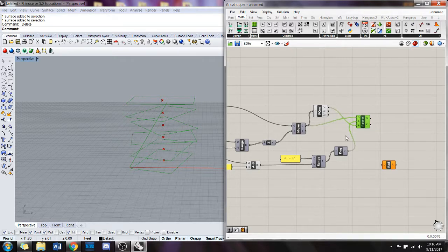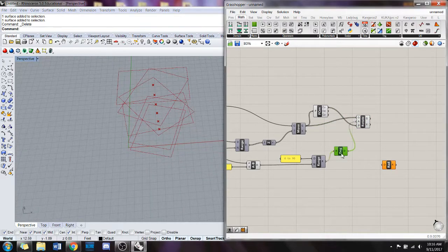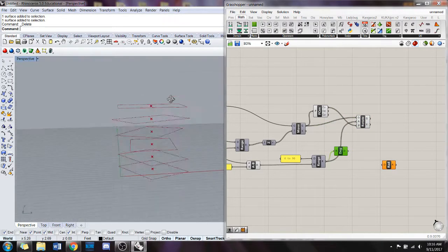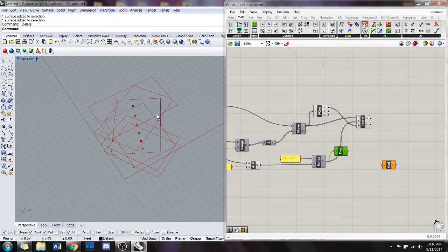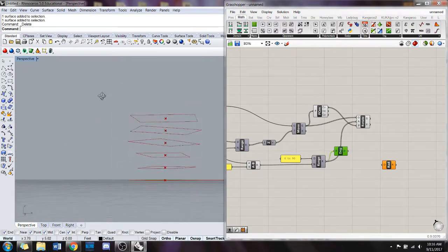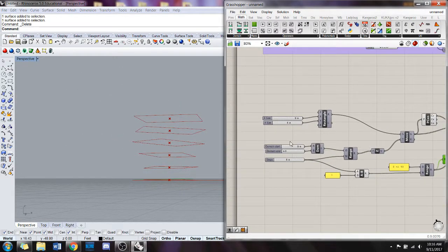So you can convert the radians to degrees before you put them into the range or after. At this point, we're rotating by degrees, or if we skip it entirely, we're rotating by radians. Either way, you have a variable rotation about the center point of each polygon. And it'll iterate through that. If we come over here and change the size of the rectangle, it'll still rotate.